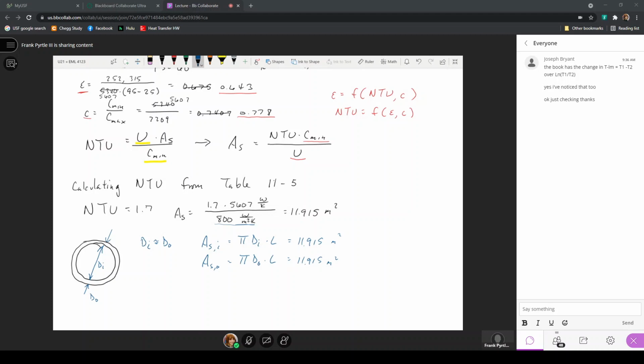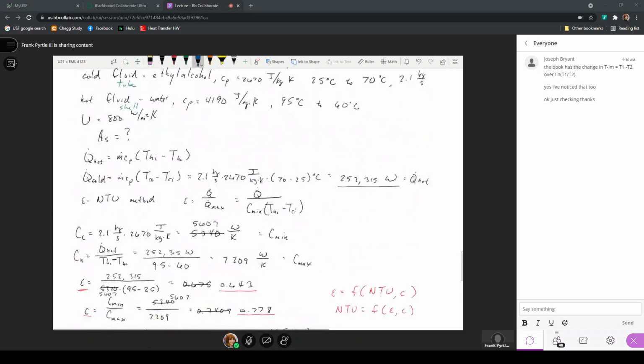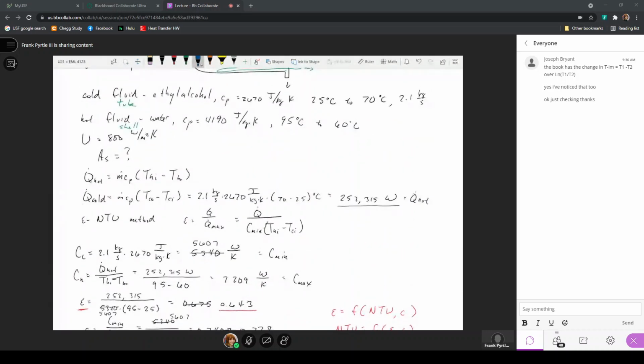have to be empirically determined, meaning that we have to actually take the heat exchanger as it's fabricated or as it's designed, connect in two fluids so that one is a hot and one is a cold fluid, and measure these temperatures. So here we have these expressions of the heat transfer rate into the cold fluid and out of the hot fluid. We can always make these calculations. We measure the flow rate.